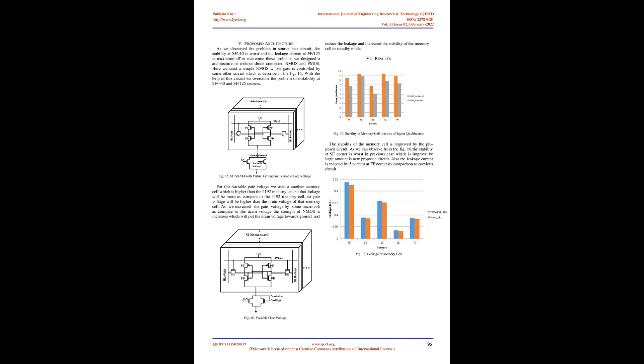Memory read. Proper operation of memory read. We need some read assist techniques because in a 6T-SRAM cell we need the same path for read and write operation. If we size the memory transistors, we can improve either read or write of the memory. If we improve the read margin of the memory, then we will lose the write margin and vice versa. So to overcome this problem we need read and write assist techniques for proper operation of memory read and